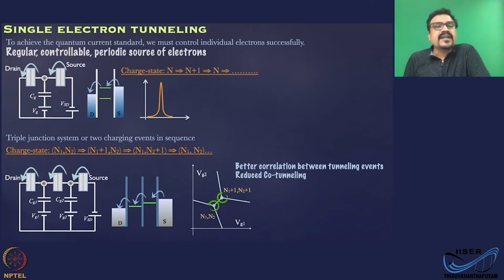So in the single electron charging regime in a quantum dot, a rough schematic is given here. We have two tunnel junctions and there is a quantum dot in the middle, which is coupled to source and drain, and this quantum dot is coupled to a gate and a voltage source, which is the gate voltage. In the low voltage regime, when the energy corresponding to the applied voltage is less than the charging energy, usually the transport is blocked and you can get current through the system by adjusting the gate voltage, and you will get a series of oscillations, and those are the Coulomb blockade oscillations.